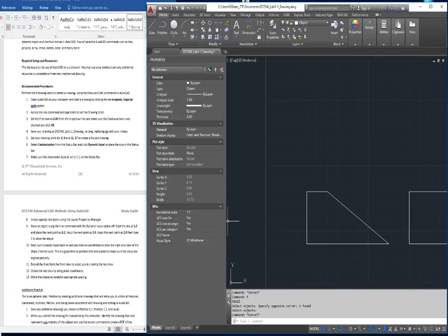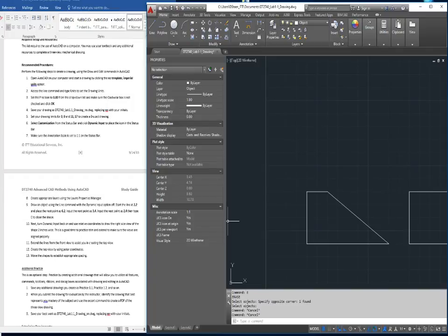The next thing it wants us to do is, there's a front view, top, front, side. So from my front view, I want to draw a top view. And it wants me to do it using polar coordinates. So line, that intersection, I'm going to say at 1, caret, 90 degrees, and it draws me a line straight up. See there? Let's do that again. At 2, caret, 90 degrees, and it drew a line straight up.